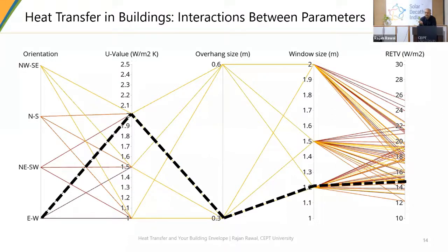Now, a Trombe wall relies more on solar radiation getting trapped at a certain point, and then you extract that into your indoor spaces with that warm air. If you have a wall which is, so let me try to explain a little bit.